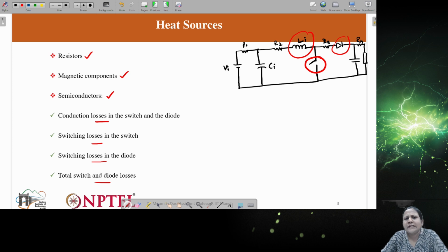Okay, generally in the data sheet they mention how much temperature device can tolerate. From the power loss we can comment on the actual temperature which will be there due to the losses in the devices, and which we can allow, so that the difference we have to take care by means of heat sink or some other method where this temperature can be taken off.